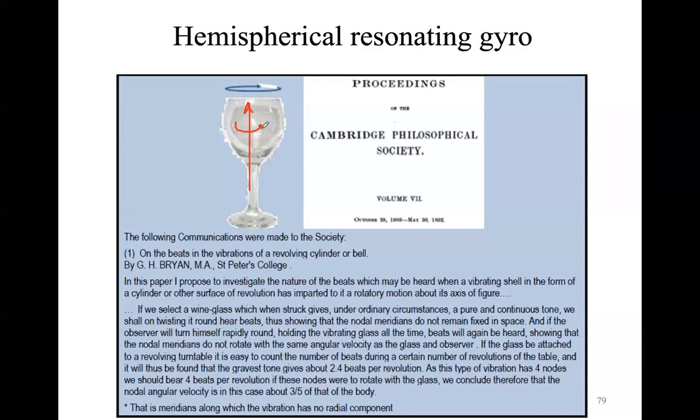The main important thing, as we're going to see, is that the Coriolis forces acting on the vibrational mode of the glass induce a specific precession of the vibration patterns of the glass that are directly related to the rotation omega at which the glass is rotated.